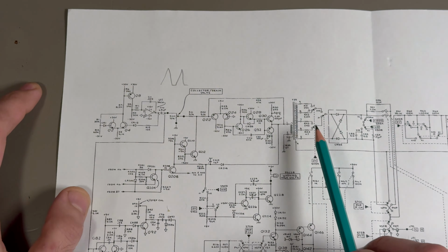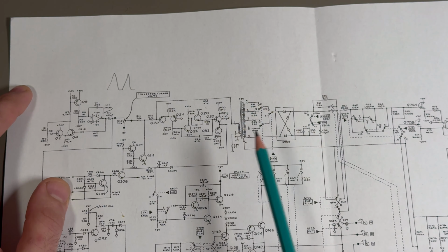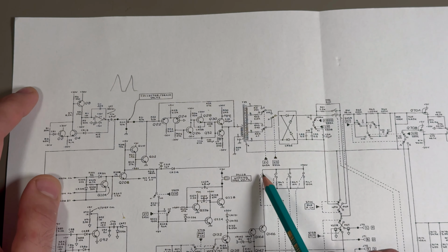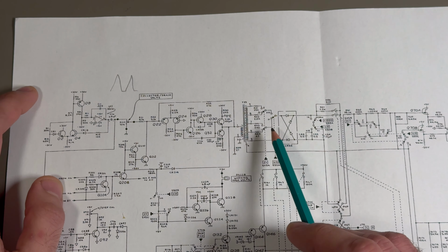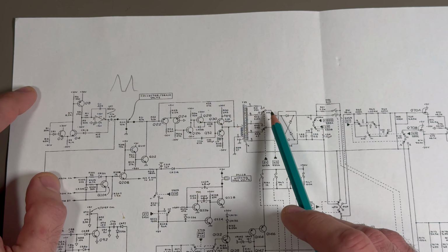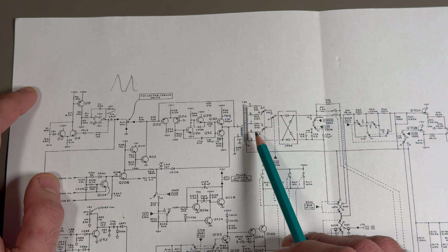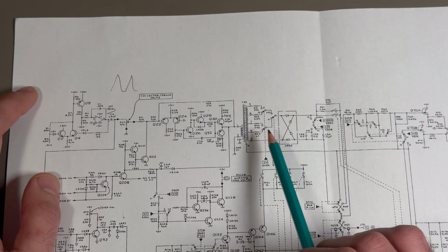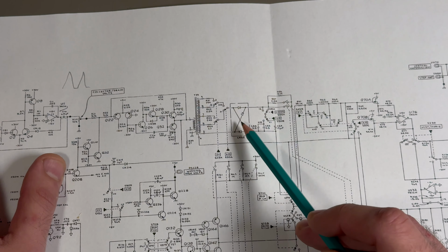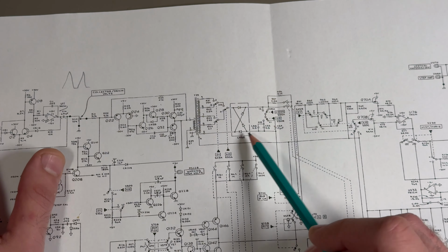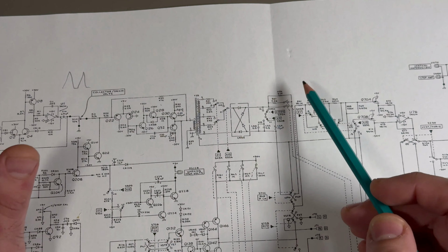This drives a transformer, which is inside the curve tracer. It's actually quite nice. And you have some settings here that are available on the front panel of the instrument. And these settings basically tap off different taps of the transformer in order to get different collector voltage sweeps. There's a bridge rectifier because for this instrument, we're only interested in one polarity. So the collector voltage always goes positive.